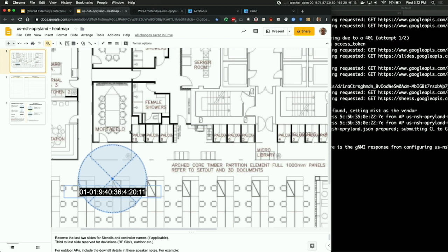They're neighbors on the map. We call it a heat map neighbor. Now it's RF, so everything depends on the walls and all that fancy stuff. But at the end of the day, if 01 is close to 02 physically, but then we look at the radio data, the RSSI, the neighbor table, and 01 is showing as closest to 09, which according to the heat map should be on the other side of the building.